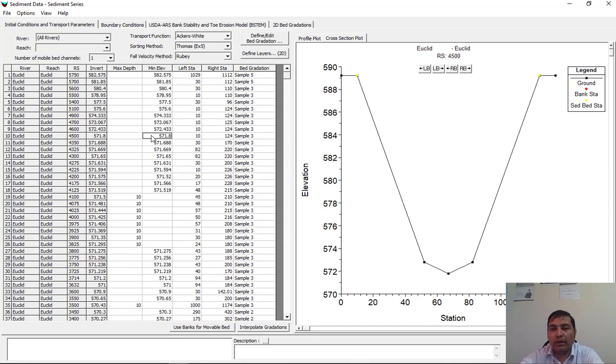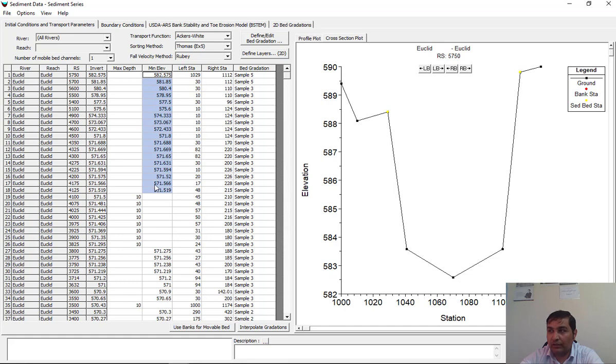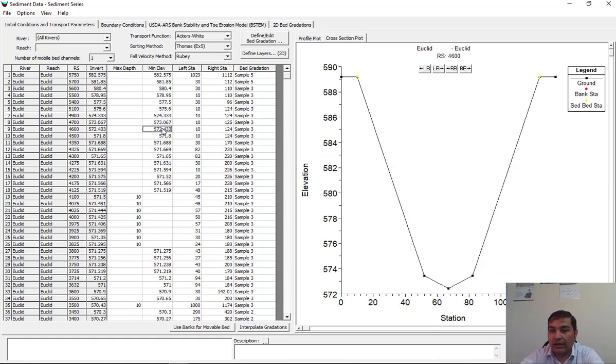I mean, if you want to model sediment transport in a reservoir, you should enter the minimum elevation column, not max depth, because in dams the riverbed is the minimum elevation, and the situation is related to deposition processes. Overall, this column is suitable for bedrock or man-made concrete channels where the bed invert elevation is constant and the model cannot erode the bed.